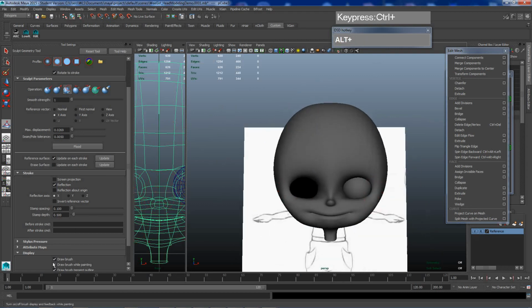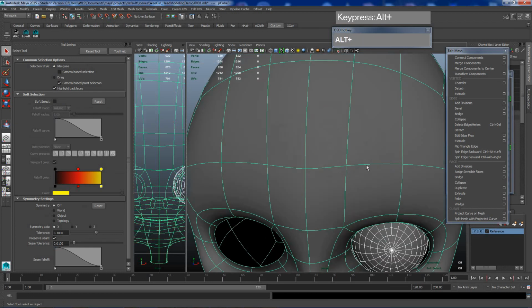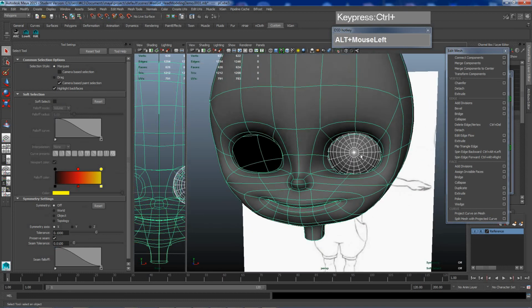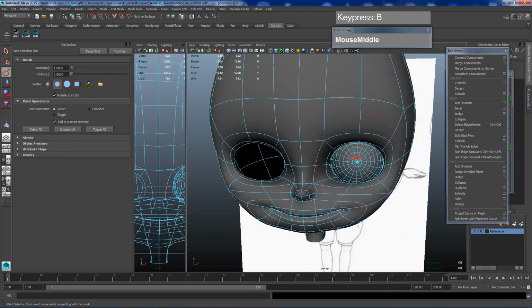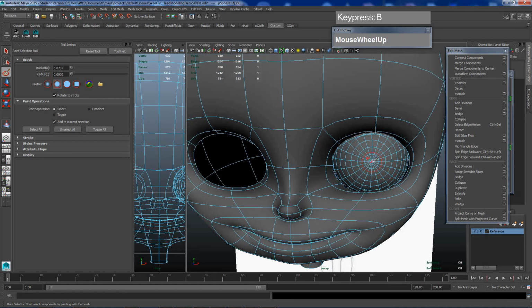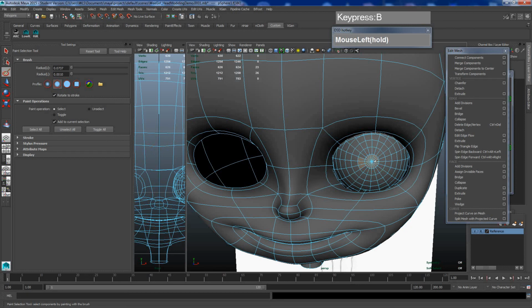Once you're done with that, you can exit from the sculpt geometry tool, and I'm going to try to add some color to the eyeball. I'm going to go to face for this sphere, and then I'm going to use the brush selection to select the center faces. Gonna paint and select the center. Right now I'm in edge mode. I need to go to face mode. So paint and select the central faces, then holding down shift and the period key, shift full stop, to increase the selection.